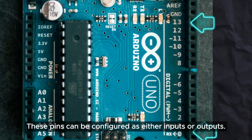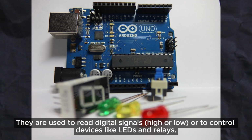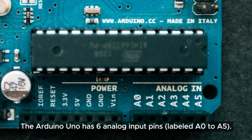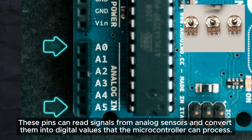These pins can be configured as either inputs or outputs. They are used to read digital signals, high or low, or to control devices like LEDs and relays. The Arduino Uno has 6 analog input pins labeled A0 to A5. These pins can read signals from analog sensors and convert them into digital values that the microcontroller can process.